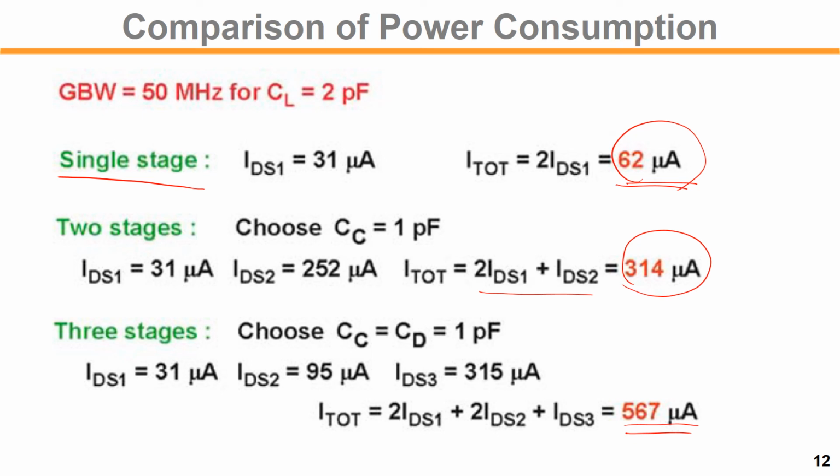So this is the example of a differential amplifier stage. The output is a single-ended output, so we count the last stage as 1x GM, but in the first and second stages, a differential pair is used, so we get 2x larger, right? By the differential structure.